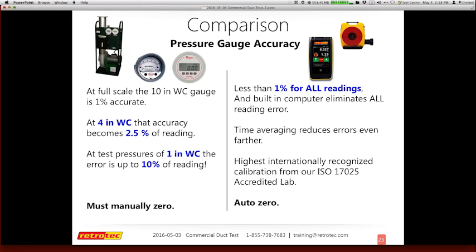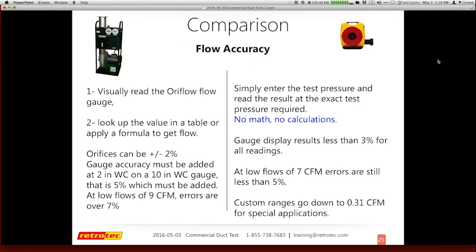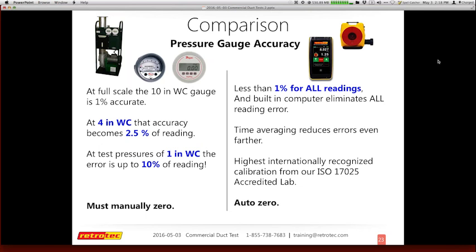The gauge, yes, Colin, go ahead. Yeah, a translation for our European friends. I asked us to talk about pascals and meters squared and so on. The easy conversion for meters squared is, we're saying 7,000 square feet, which is roughly about 700 square meters. And here, 4 inches of water column is 1,000 pascals, and 1 inch of water column is 250 pascals. So back to you, Joe.